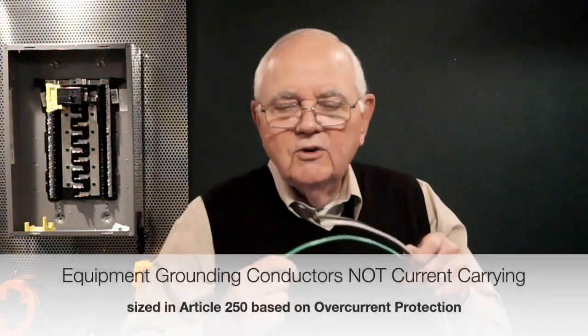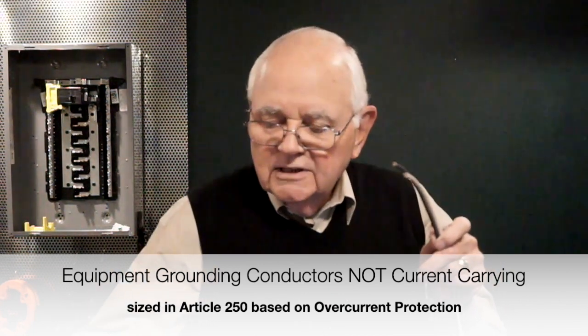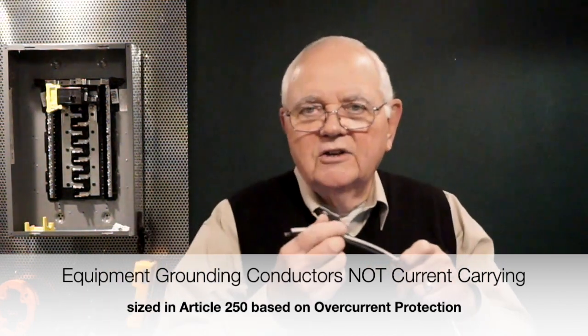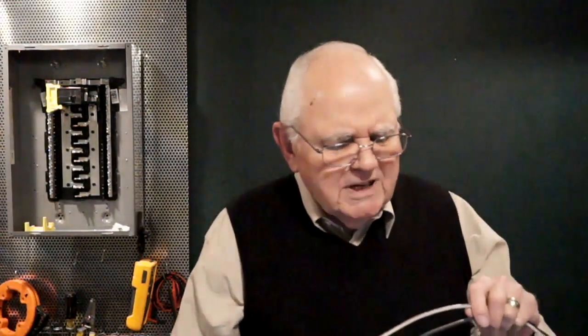By the way, the green wire, is it a current carrying conductor? I hope not, should not be. So we don't count it when we do our ampacity calculations. Does it count for conductor fill? Absolutely. What about ambient temperature? Let's say I'm going to run these in a really hot area, through a boiler room or something like that, where the ambient temperature is going to be 100 degrees. The ampacity properties for these conductors were based on an ambient temperature of 86 degrees Fahrenheit. So I need to go back to another table and correct for ambient temperature.